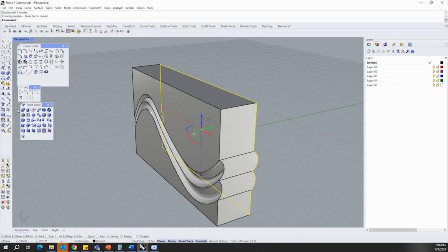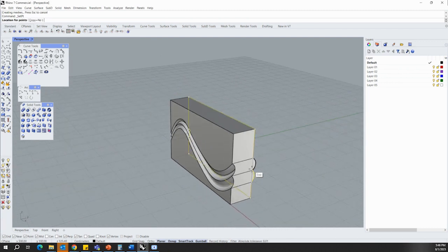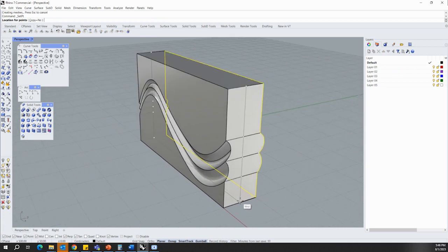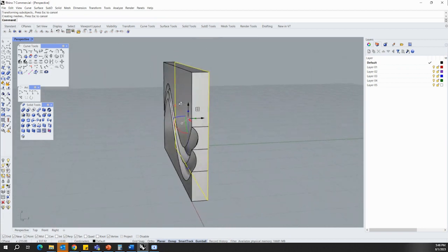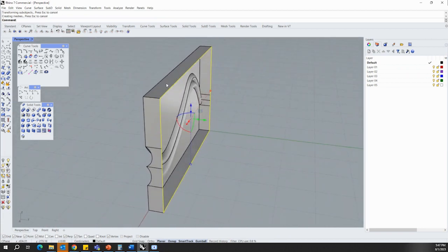For that, you can go to the move tool. Here if you extend this arrow, you will have this option called set XYZ coordinate. If you click that, it will ask you which axis it has to be set. I need it only in the Y direction, so it will extrude only in that direction, and I will set my extrusion only up to this point. Got it, right? We are getting the box out of it.